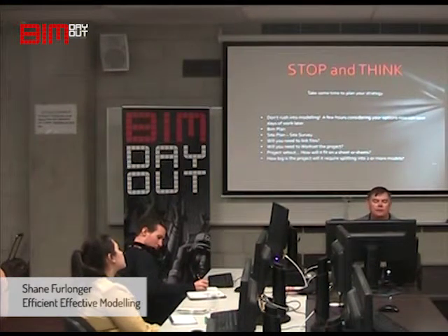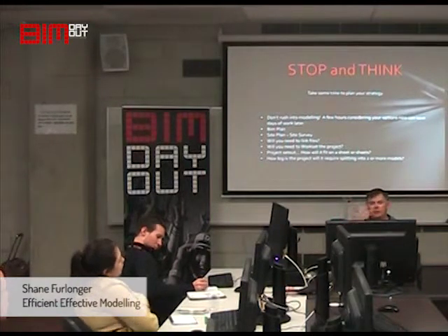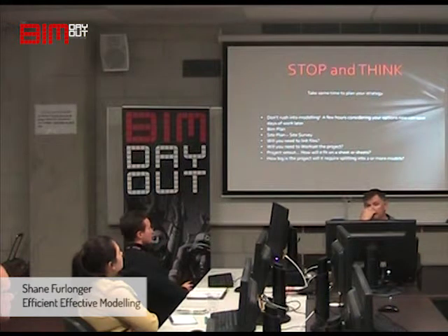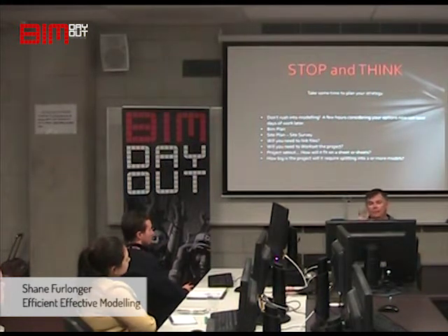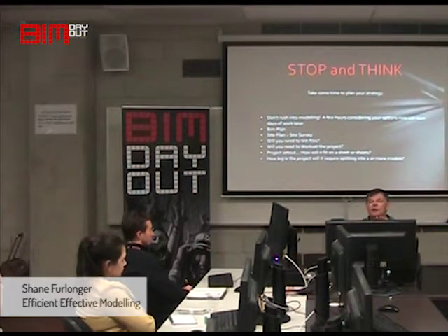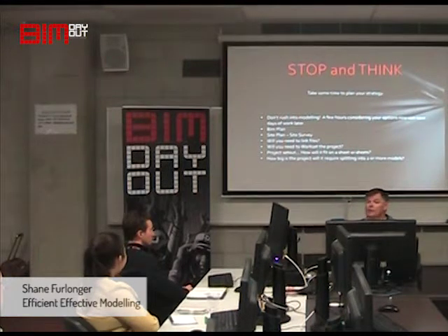If you look at the floor plan of your building, let's say you've got a design already, and you're looking at your floor plate, and you need it to fit on an A1 or an A0 or an A3. Will it fit at 1:100, 1:50? If you're going to be doing 1:50s, will the building fit on that sheet? Or I'm going to need to split the building, and by splitting it, I mean using a match line, and then having dependent views.